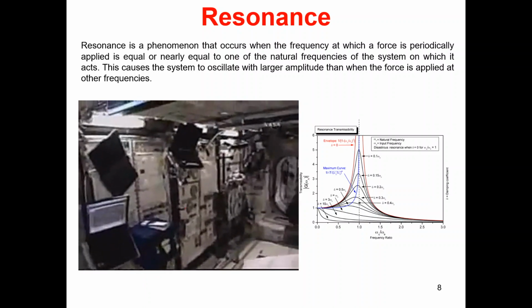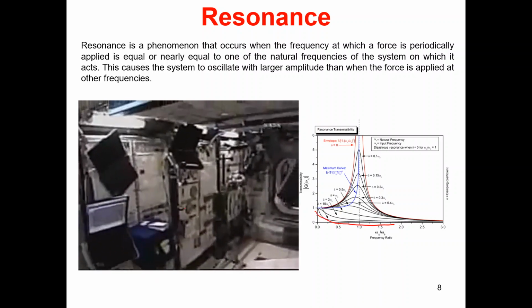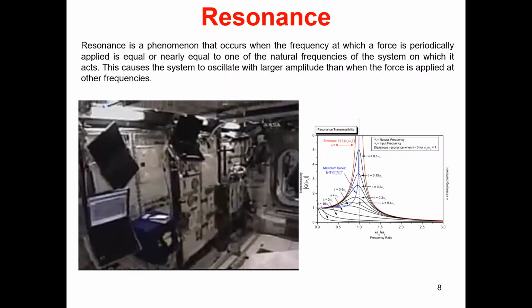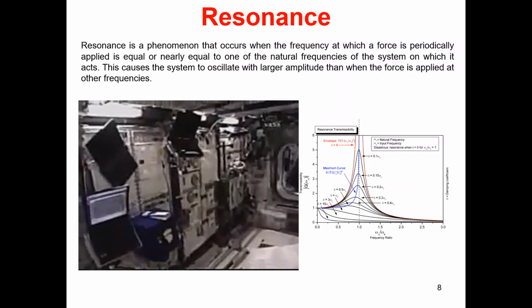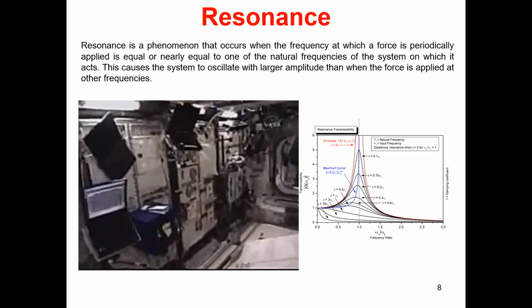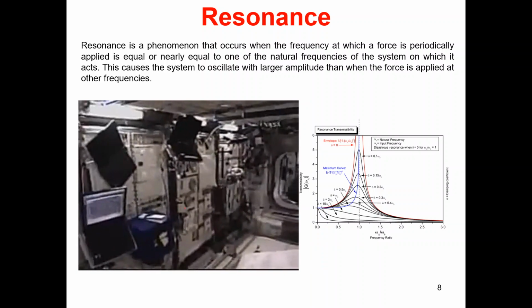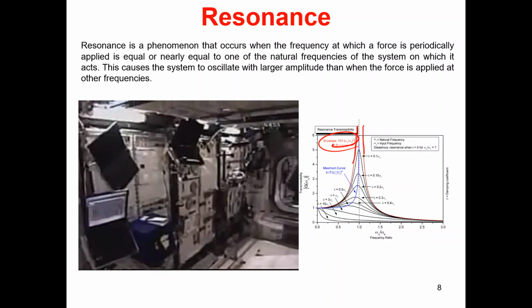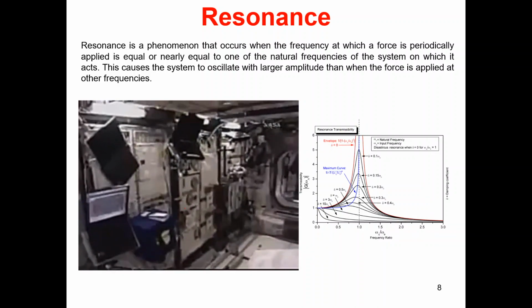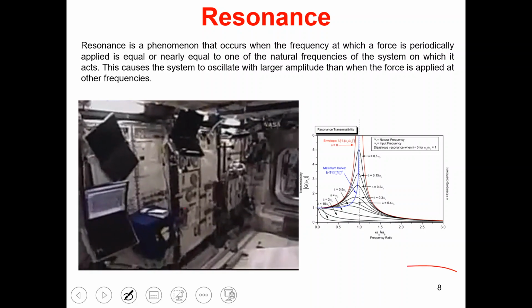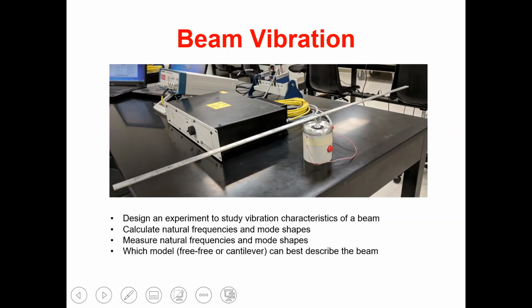As you can see, for larger deltas, we don't get any oscillations. Everything is going to be normal. But then as you decrease the delta and the delta becomes zero, it means that your natural frequency and input frequency are coming closer, and this is where the disaster happens, when delta becomes zero. And this is where you're going to see very high oscillations that you don't want to see normally.